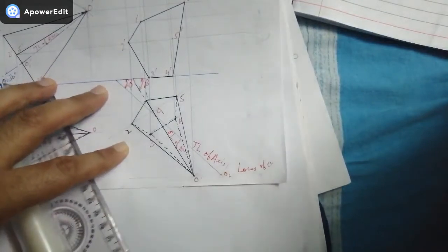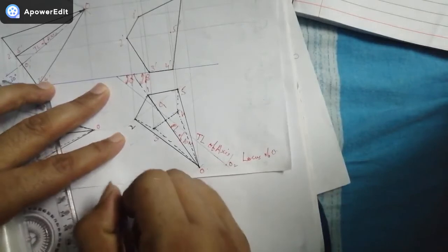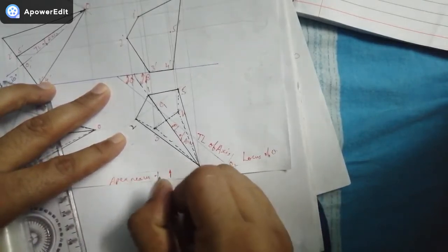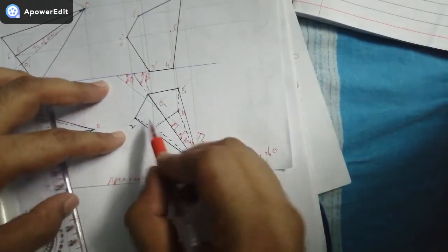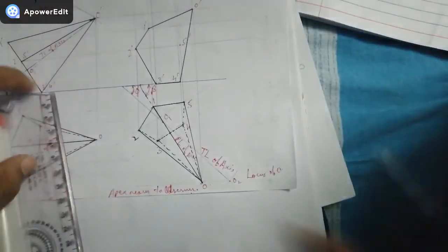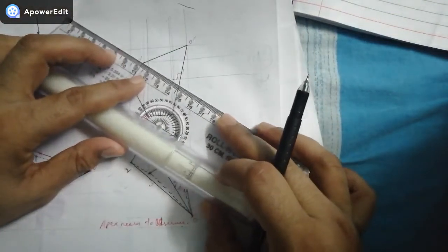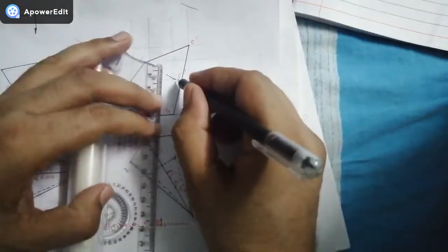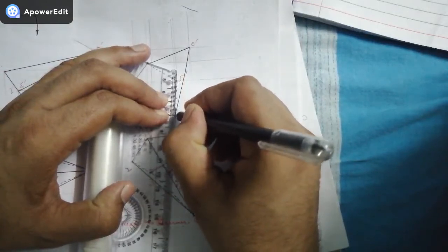Even if I see over here, if I mark it very clear cut over here, I can name it as apex nearer to observer. So that means, my dear friends, whatever is there from O to 2, beyond that everything is not visible to us. So 1 dash to 5 dash and 5 dash to 4 dash, everything, my friends, is going to be hidden.